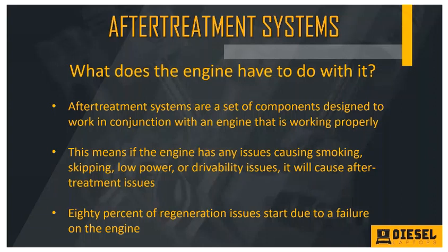Okay, so do filters fill up with ash on their own? Absolutely, that's what they're designed to do. But you're talking 200, 300,000 miles. If you've got a filter that needs to be serviced or a truck that needs to be regenerated daily, and you've only got 50, 100,000 miles on this truck, you've got an upstream problem that's leading to this. So we have to address that, okay?